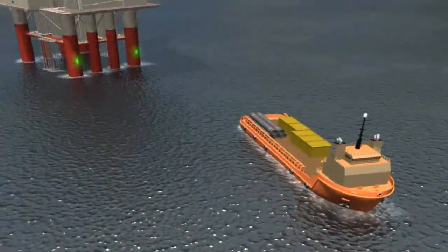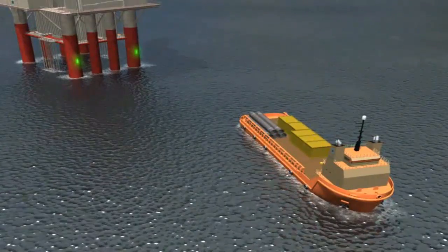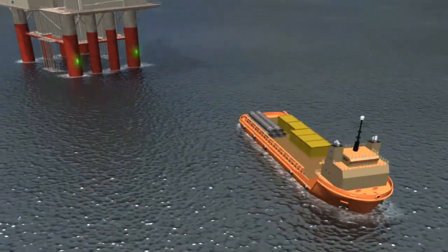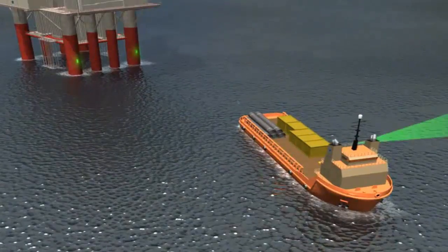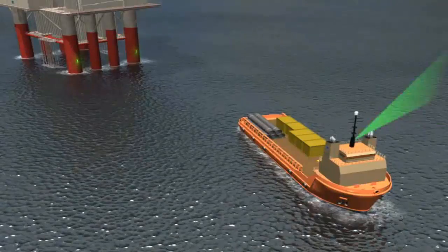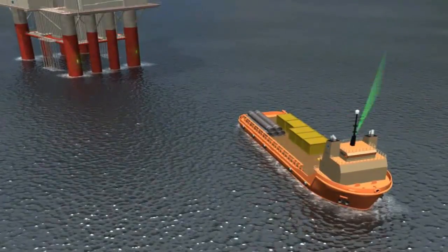The blanking zone is the area in each rotation where the laser is turned off and not searching for targets. It's usually set to cover the area of the vessel's superstructure, which could create false readings on the Cyscan display. During normal operation, the blanking zone requires no adjustment. However, there may be some instances where this is necessary.